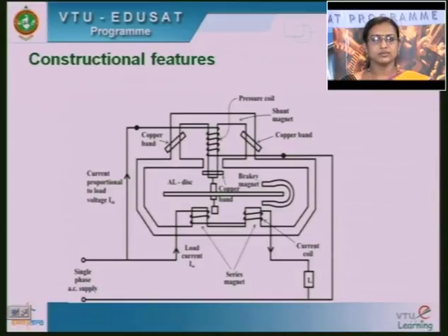Now, this is due to the torque produced by the current flowing through this shunt coil and the current flowing through this series coil. And then you control the rotation of this disc by using this brake magnet.